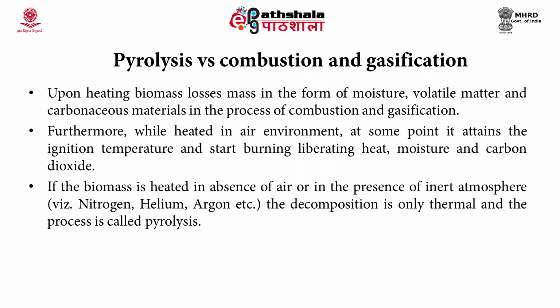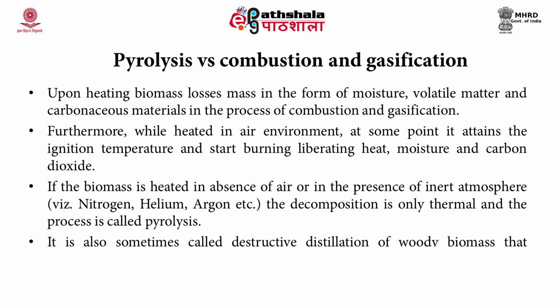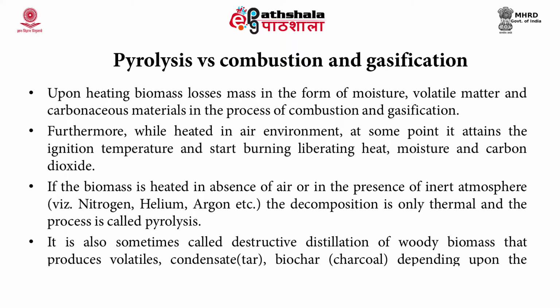So, pyrolysis happens in the absence of air, while combustion and gasification occur in the presence of air. In combustion, excess air is used; in gasification, a limited supply of air is used. Pyrolysis, known as destructive distillation, produces volatiles, condensates like tar, and biochar, which is normally charcoal, depending upon process variables and the reaction temperature.